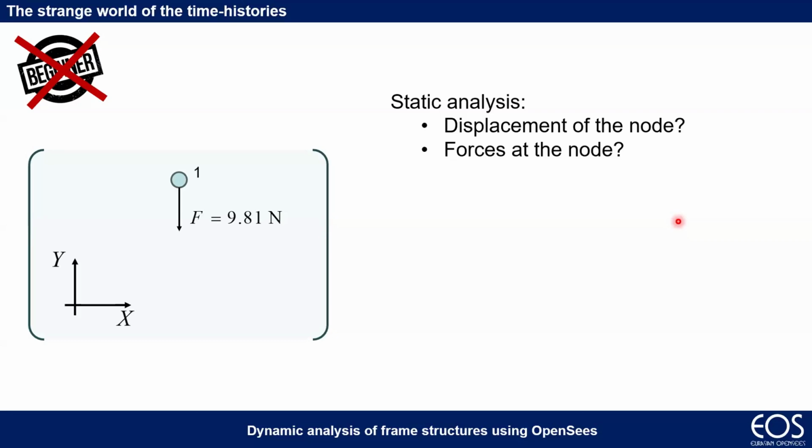Infinity? How did you say infinity? No boundary, no restraint, no constraint. I'll change the question, okay? How do you compute infinity? Okay, displacement is the inverse of the stiffness matrix times the forces. But what's the stiffness of this structure? Yeah. There is not any stiffness. It's no stiffness. Zero.